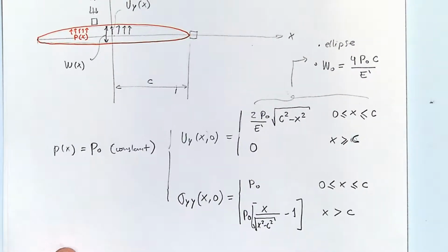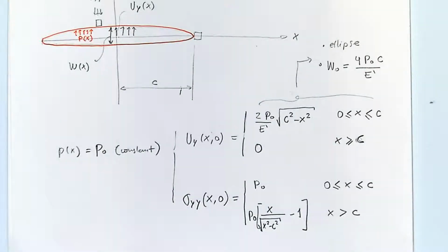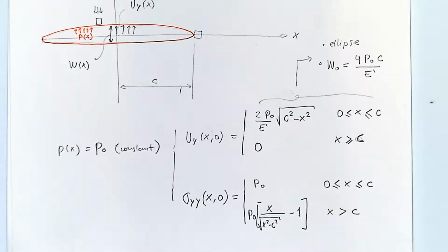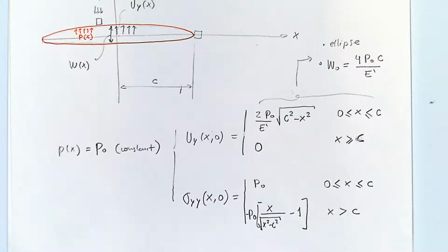Okay, so according now to this equation, I gave you the solution, so you have a solution in there. What is going to be the stress at the tip of the fracture for x slightly bigger than C? Infinity, because this one tends to 0, right? This one tends to 0, and probably I should add a negative sign over here to show that that's tension.